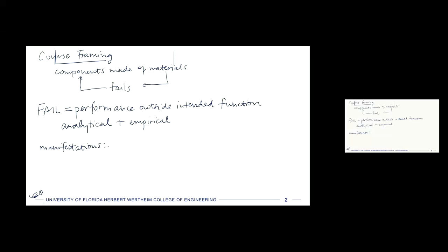All right, so the first one is elastic deformation. And you might think, well, if things are in elastic deformation, then they're working as intended. They're not breaking. But if something is bending more than you would expect, like let's say your chair leg, and it bends so much that it goes too far, then the chair could fall down, right? Even though the material itself did not break or have plastic deformation, right? Elastic deformation means there's something out of place, and that could be considered a failure. The one that we're most familiar with is plastic deformation.